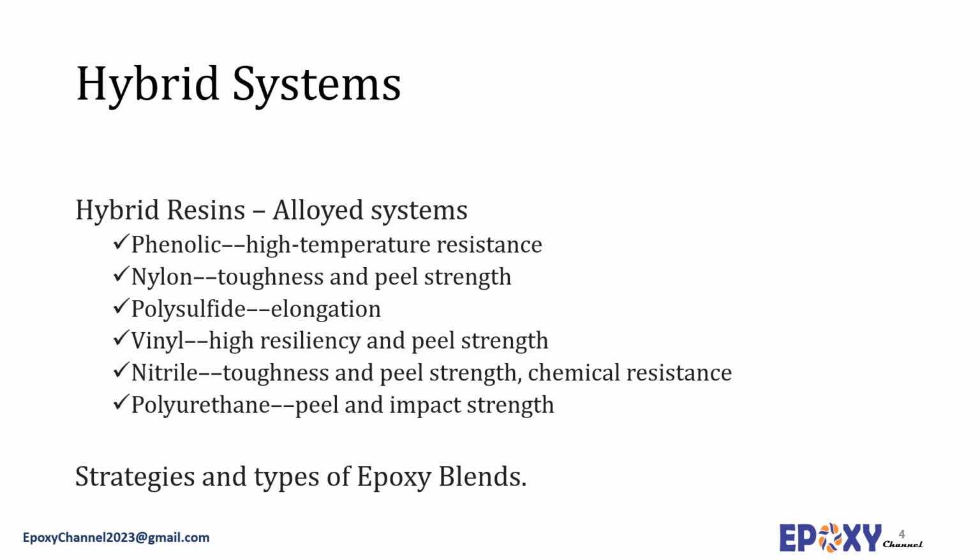Hybrid resins have been used to improve the flexibility, thermal shock resistance, elongation, heat distortion temperature, and impact strength of unmodified epoxy adhesives. However, there may also be some sacrifice in certain physical properties due to the characteristics of the additive. These alloys result in a balance of properties, and they almost never result in the combination of only the beneficial properties from each component without carrying along some of their downsides.